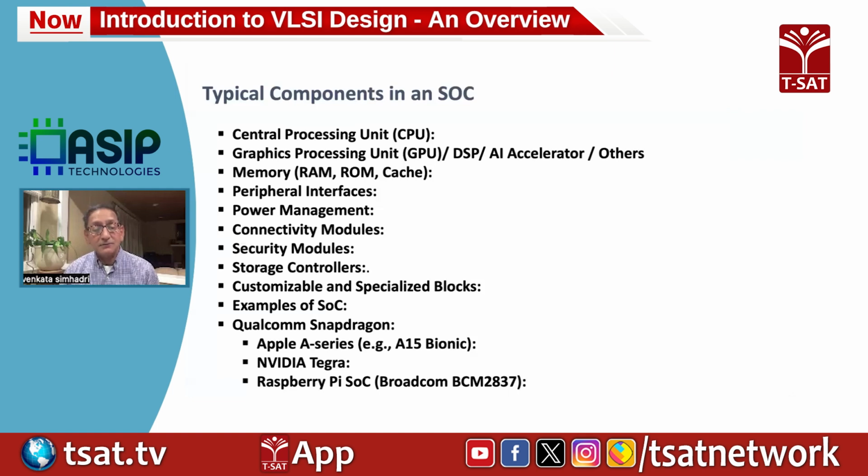So these are different modules you keep integrating into an SoC, like storage controllers, and if the SoC is talking to a sensor, sometimes it might need a custom cell, for example, an ADC, analog to digital converter, to talk to a sensor outside. Some examples of SoCs: Qualcomm Snapdragon that used to get into tablets and other devices. Similarly, Apple's A series chips, NVIDIA's Tegra. So these are some examples.